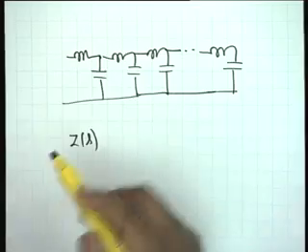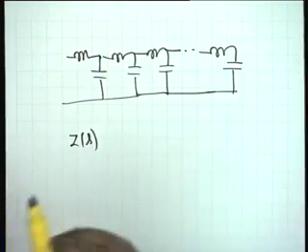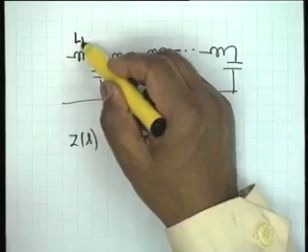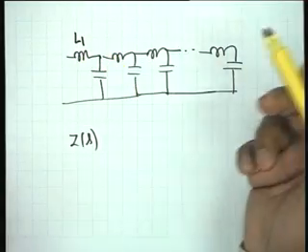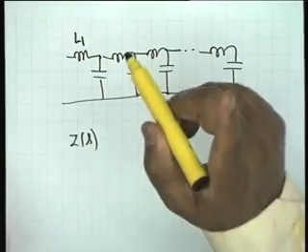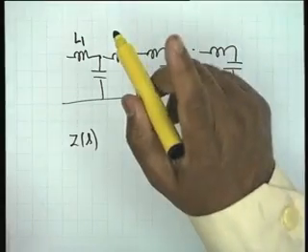So you take the reciprocal and start with the admittance and admit this capacitance. This will be the first capacitance. The first element will be a capacitance. So this inductance, the first inductance L1, may or may not be present. It shall be present if the impedance function has a pole at infinity. It shall not be present if the impedance function has a 0 at infinity.